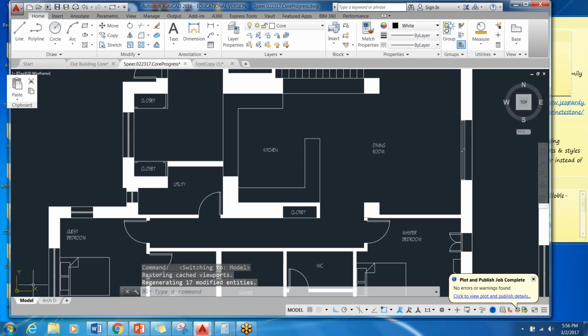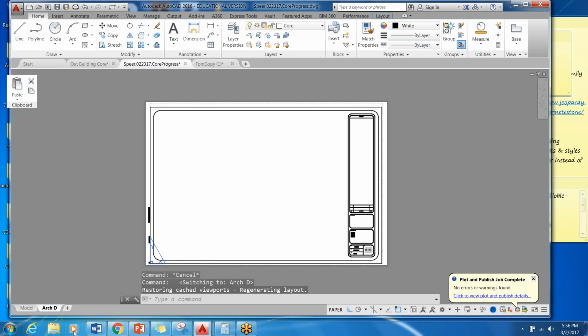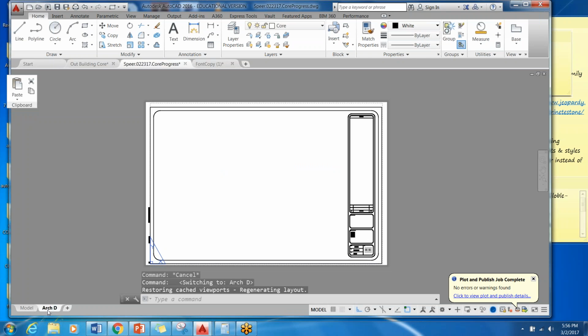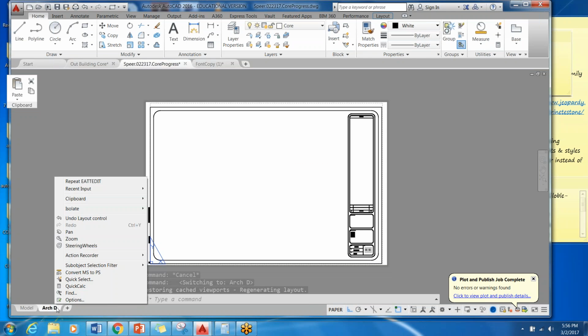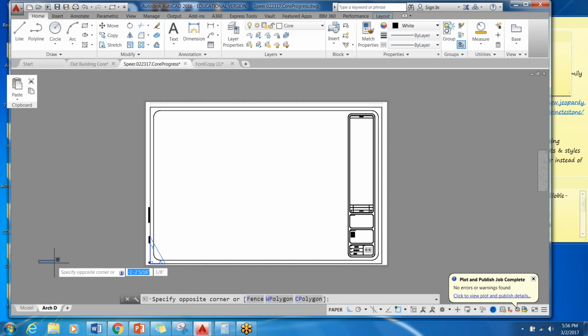You can print from model space. It's pretty archaic. Well, I feel bad about that. That's what I learned to do when I was a student. That's how Cheryl most often prints, I think. But it's not as precise and clean and beautiful, and you have to bring in your own title block instead of having this nice setup one. You have to scale it a special way and rotate it. Why do that when we can create these sheets and then right-click them and adjust what we need to from inside this layout? It's nice and orderly.